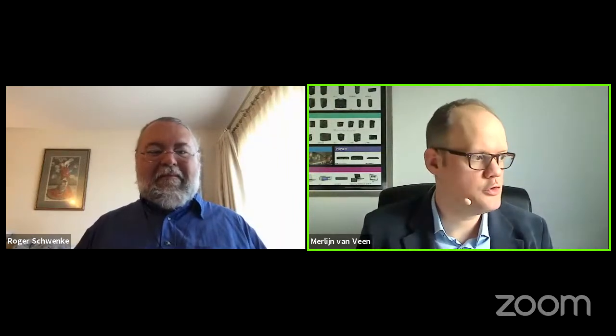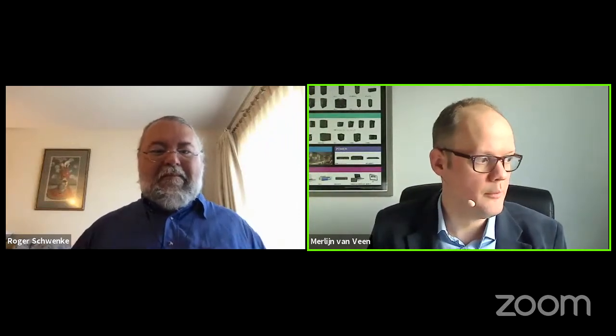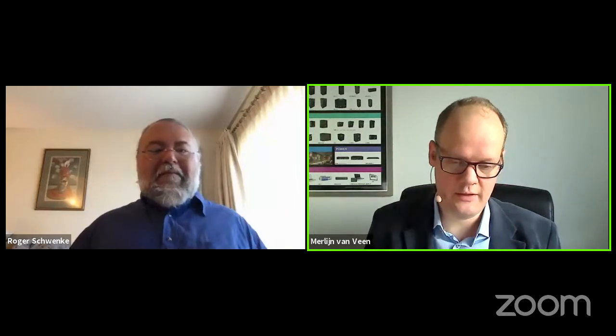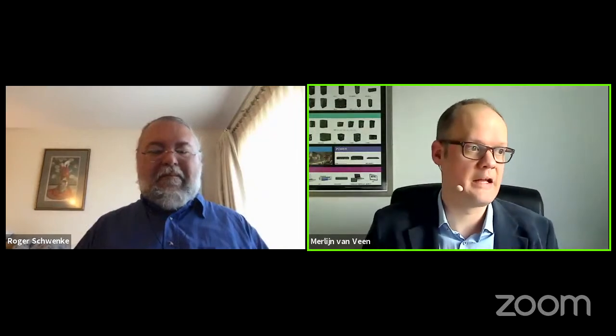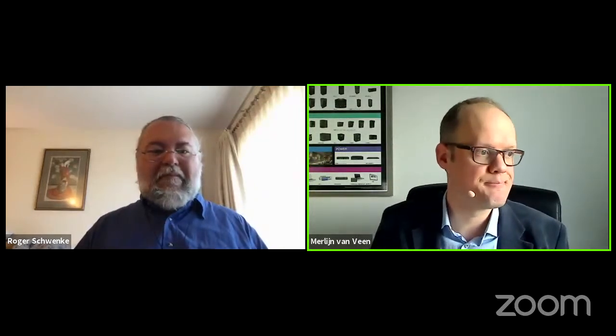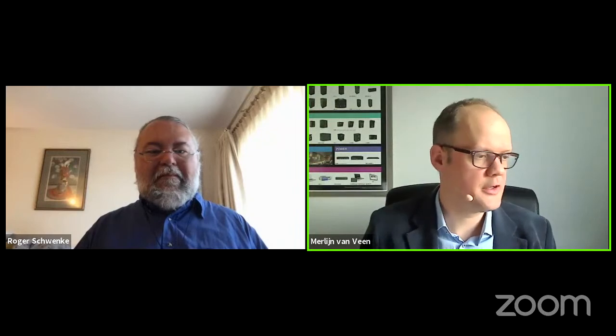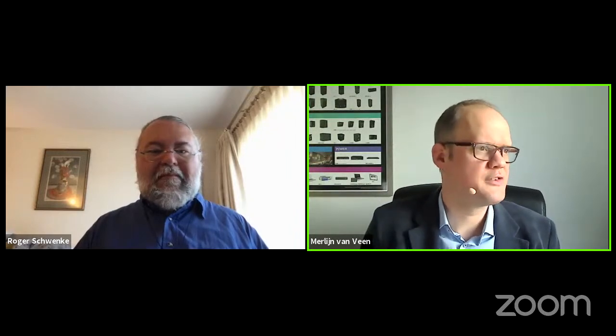Yeah, you would really need a gratuitous amount of phase shift, i.e. group delay, to start to affect the coherence as a function of bias, as it's known. In the interest of this exercise, the bias that group delay might introduce is negligible in light of the time records that are typically used for doing this kind of analysis.